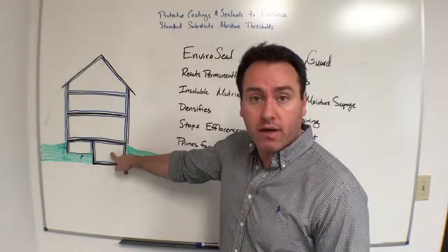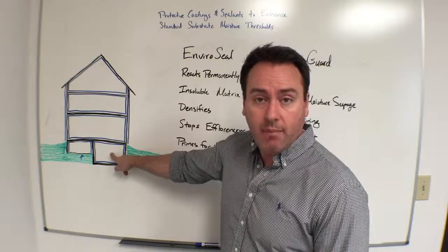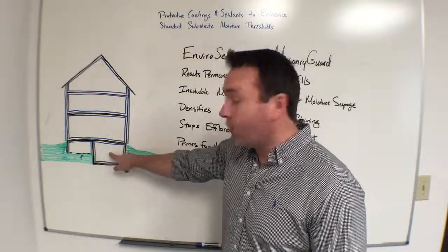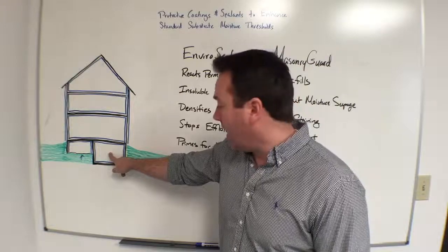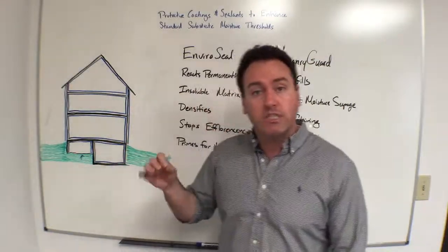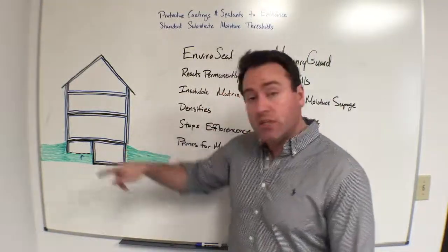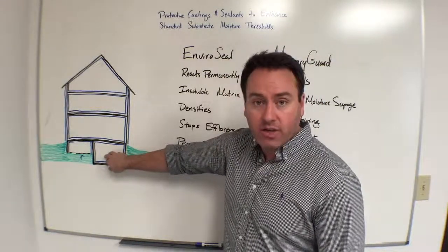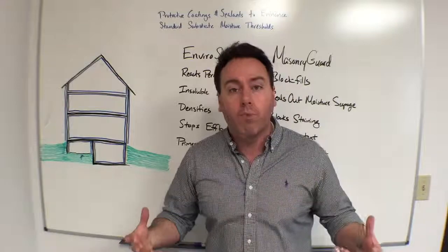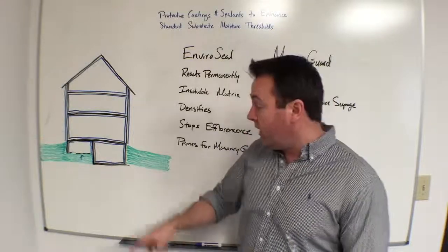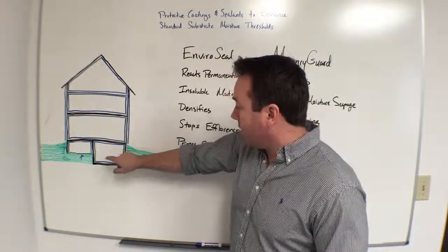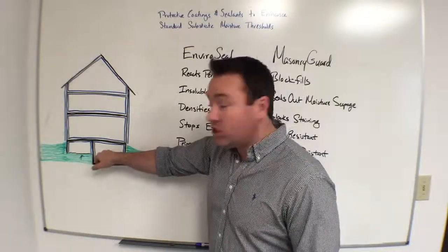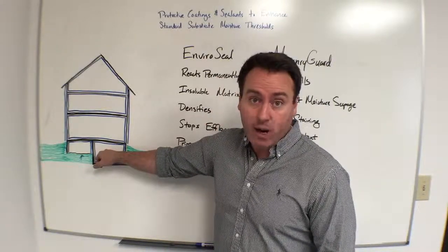Depending upon if you're in a conditioned or an unconditioned basement, that's going to vary. But let's just assume, for the sake of this video, that we're dealing with an unconditioned basement here. So we've got those three forms of moisture just like a crawl space. The advantage with the basement is we have more air mass to deal with so that we can absorb more moisture, right? But if you have periods where condensation is occurring due to hitting dew point, you've got more moisture release as a result of that as well, potentially.